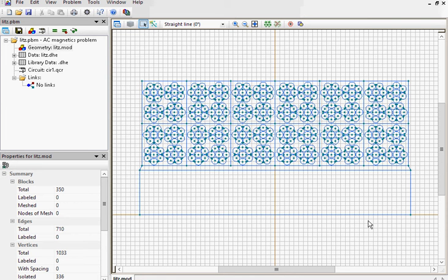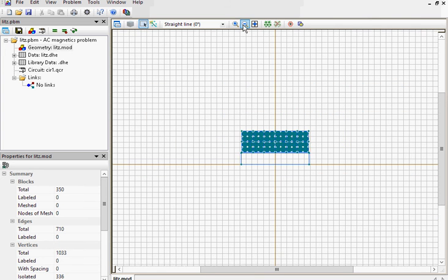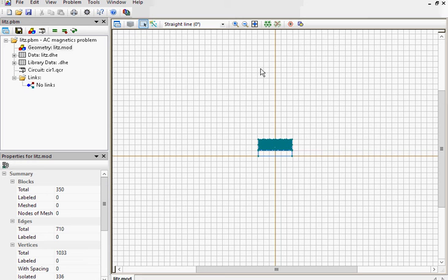In axisymmetric problems, the axis of rotation is a horizontal one, and we should draw only the upper half of the cross-section. Here you can recognize conductors, insulation, and the core. In fact, the magnetic field is distributed not only in these parts, but also in the air outside. QuickField cannot simulate magnetic field distribution in infinitely large space, so we need to restrict the simulation area.